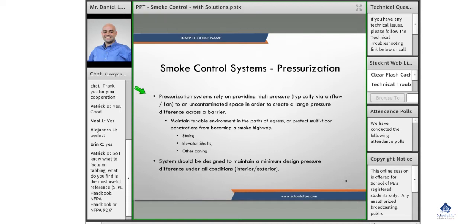Shafts are very scary when it comes to smoke because you have completely removed all horizontal assembly, all barriers, everything else. That's why there are so many rules sometimes in the model codes around your shafts, around your penetrations to your shafts, and holes in those horizontal barriers, because that keeps the smoke on the floor. And as soon as it hits an unprotected shaft, it's popping right out of the building, and you can have people lose their lives many, many floors away from the fire.